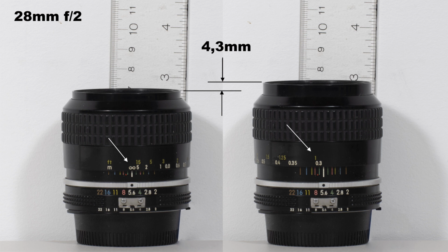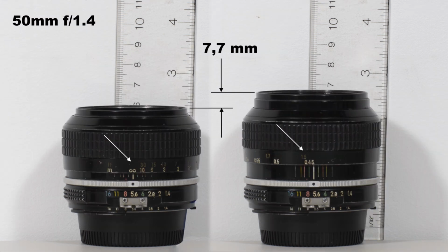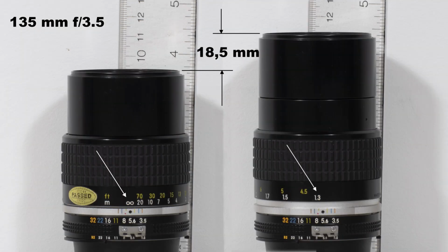This basic principle of focusing a lens from infinity to minimum focus by moving the lens away from the sensor applies to most of the lenses on the market. For example, on a wide angle 28 millimeter lens, the travel distance is about 4.3 millimeters. For a 50 millimeter f/1.4 lens, the travel is about 7.7 millimeters. For a 135 millimeter lens, the one that we just checked, the travel is about 18.5 millimeters from infinity to